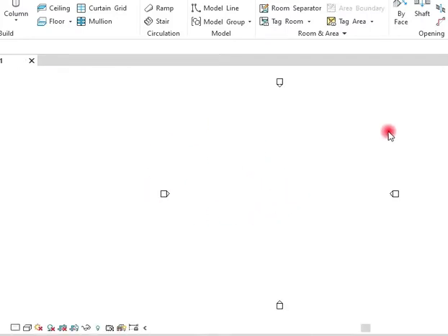There are many things you must do first in doing your drawing. Number one, you need to know the reference point where you will start your drawing, which is very important in Revit. As an engineer or an architect, you need to know your 0,0.